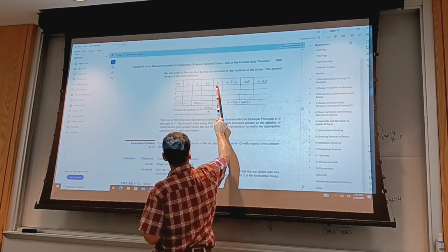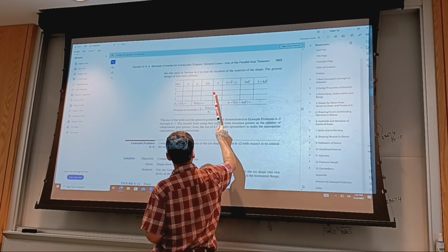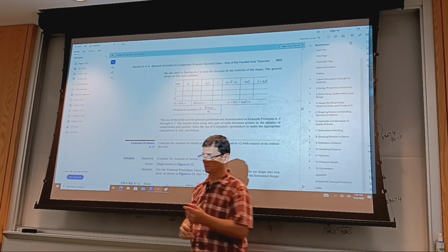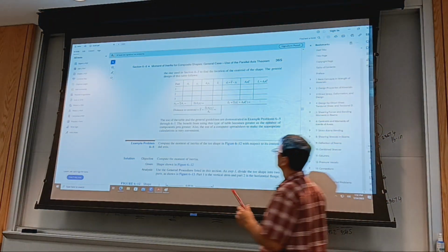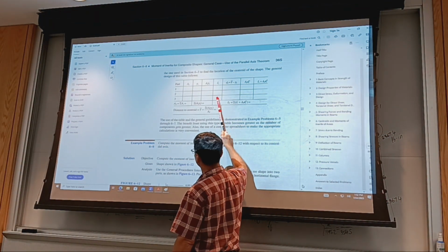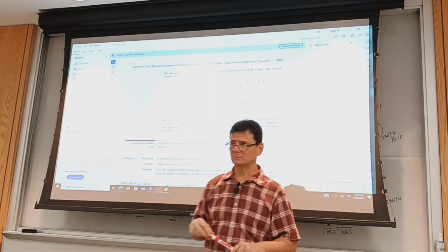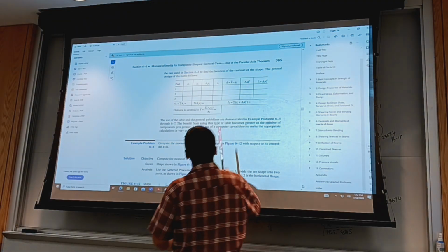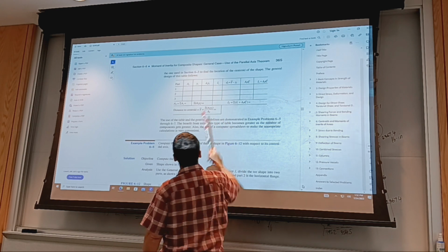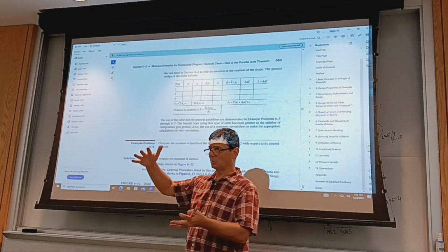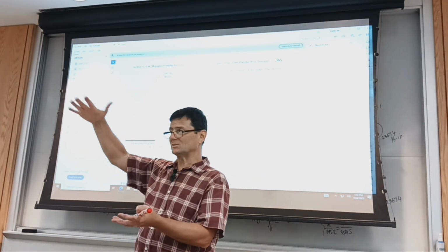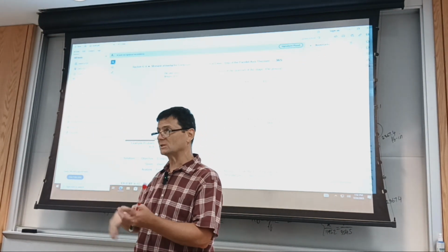Okay, so for area moment of inertia, to calculate the area moment of inertia of the assembly, you get the centroidal moments of inertia of the individual shapes. So for that, you go to the back of the book, Appendix 1. So you have rectangle, circle, whatever shapes, half a disc. These are all centroidal figures. They're the smallest. So area moment of inertia is about an axis. Its minimum is when the axis passes through the centroid, if you remember.